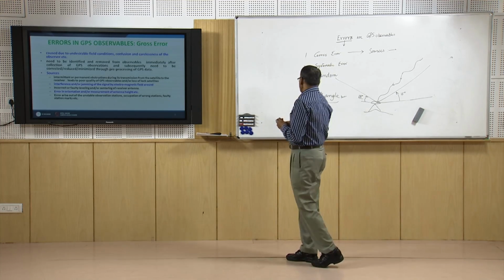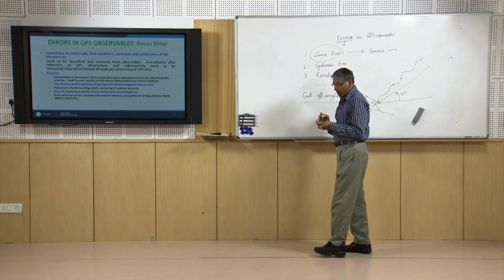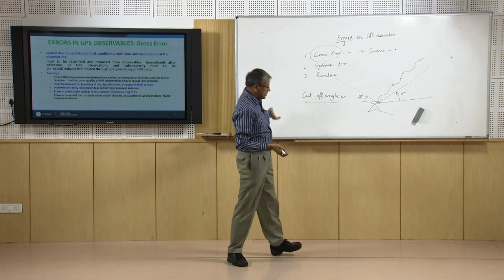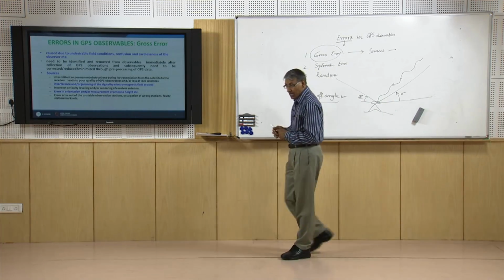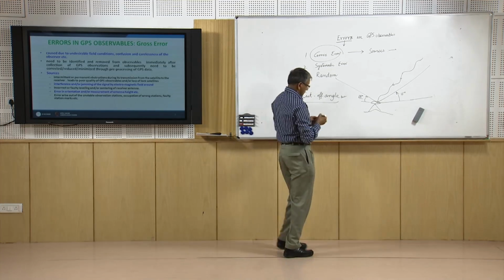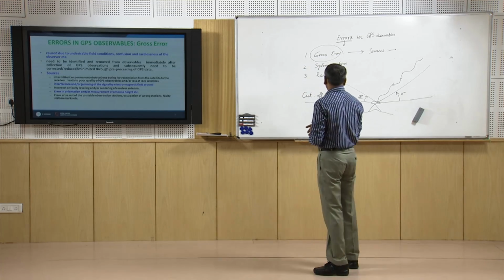So the best way to avoid gross error is to take care before starting our observation. Once the observation is available, we have to check whether there are any gross errors, and those data have to be removed from further computation.